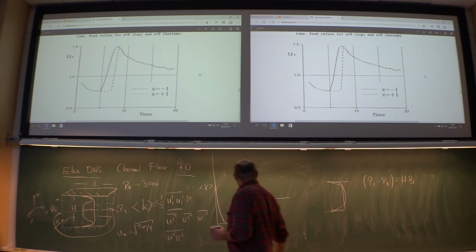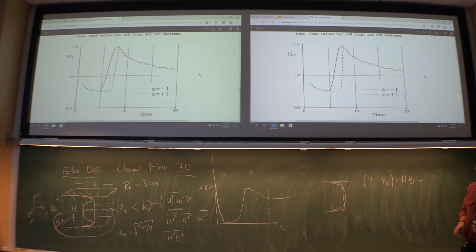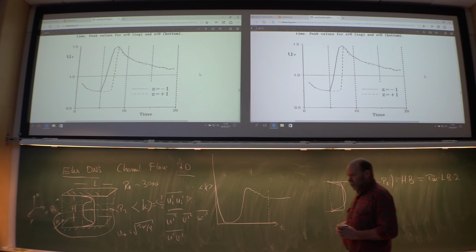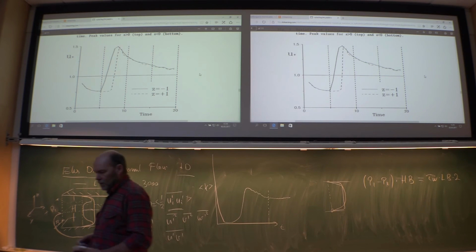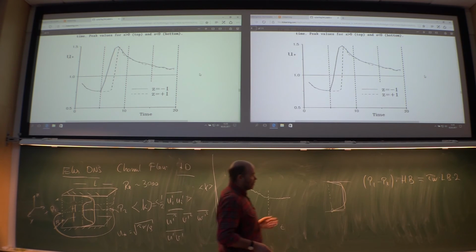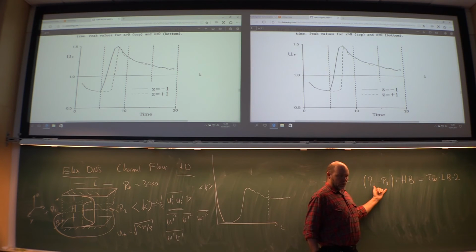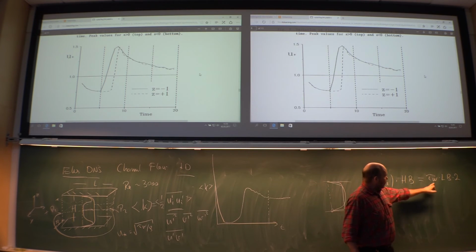So there you have one force, which has to balance exactly the wall shear stress multiplied with the plate area, L and B, and I had 2 of them. So from that equation, before you begin, you know what the wall shear stress should be. You can calculate it in advance because it is externally given as a driving force.